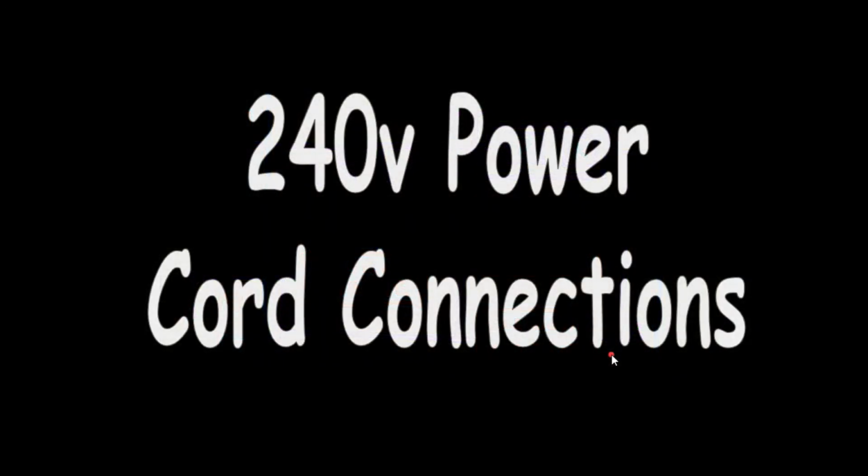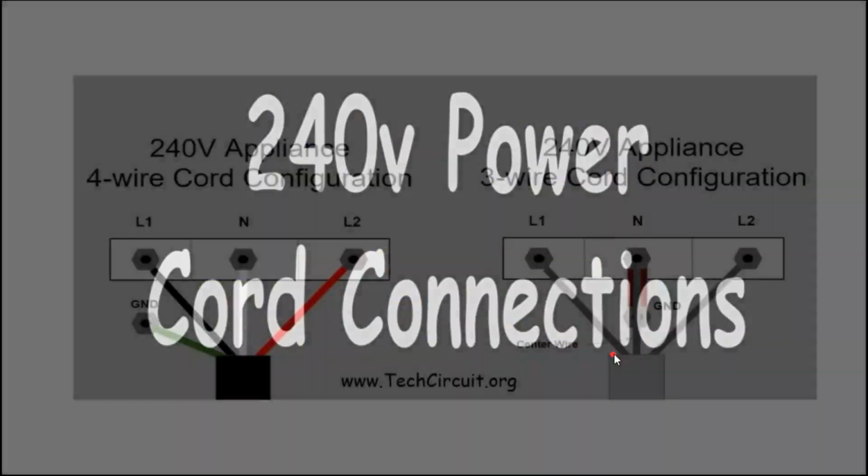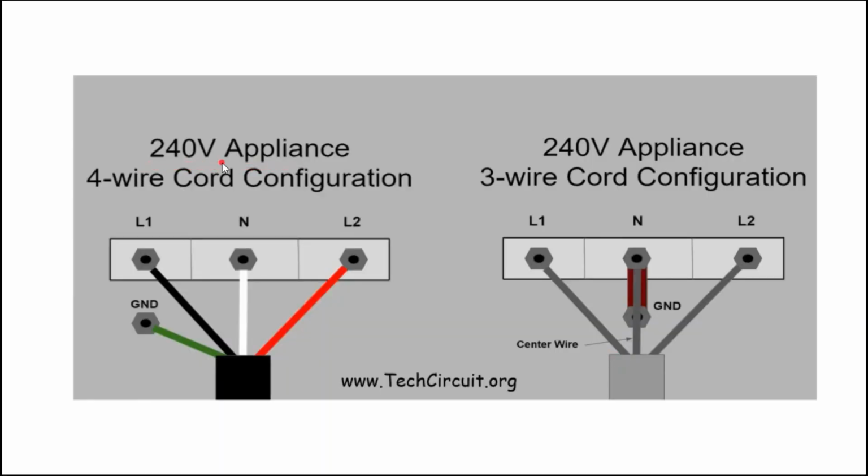Let's talk a little bit about 240 volt power cord connections. This is a typical 240 volt appliance 4-wire cord configuration. On this lug here on the left, you typically have L1, which is the black wire, neutral in the center, and then L2 over here on the right. And you're going to have a separate ground wire that is actually bonded to the cabinet for the metal part of the appliance.